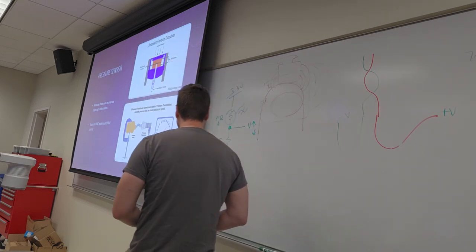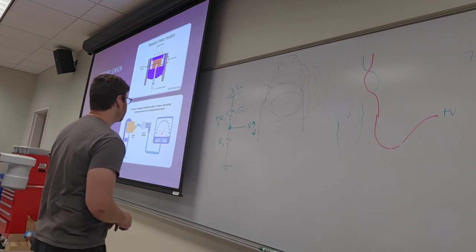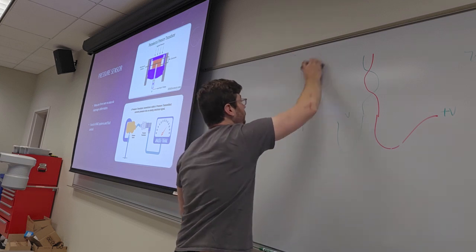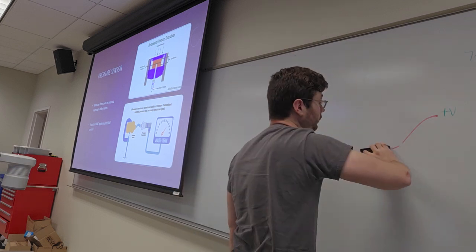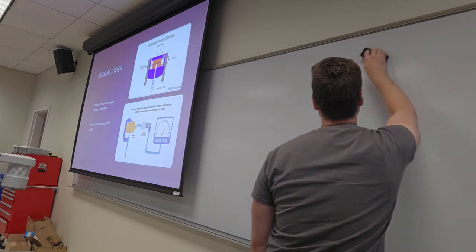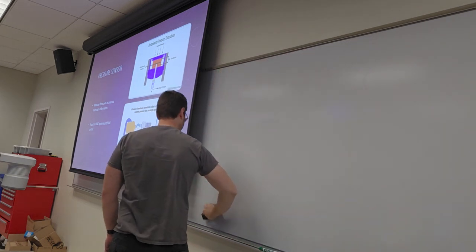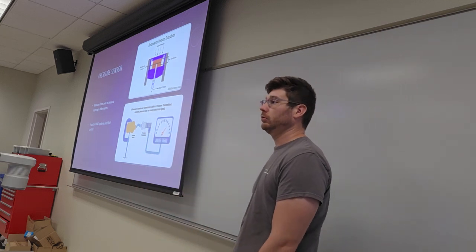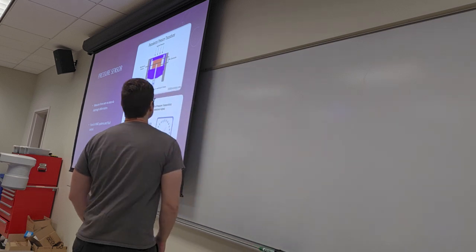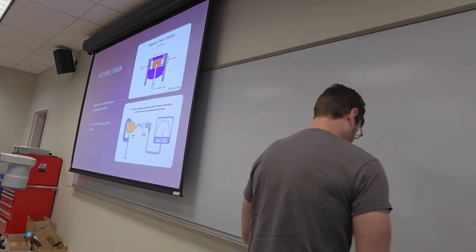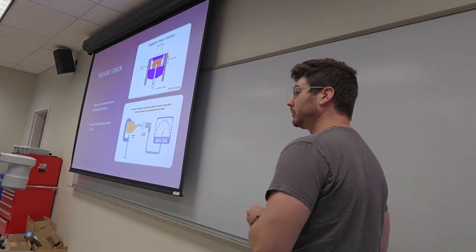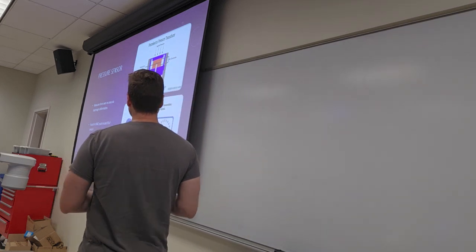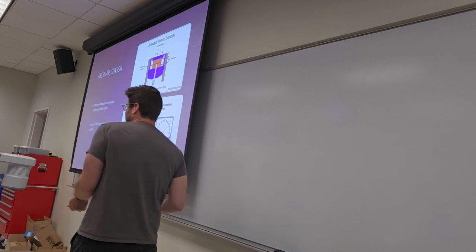We also brought up the idea and the flexibility of a pressure sensor, particularly a differential pressure sensor. Okay. So a lot of people who aren't in the industry, you know, I keep seeing in the industry, but if you're using a PLC in an industrial environment, you're probably measuring something. Okay, if you're measuring flow or pressure or volume or weight or mass, whatever. Pressure sensors have a home in almost all of those places, right? To measure weight, you use a pressure sensor. To measure flow, I'll show you that again in a second, how we can do that. All the way to, you know, the literal pressure inside of a canister.